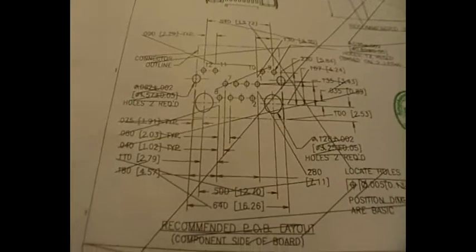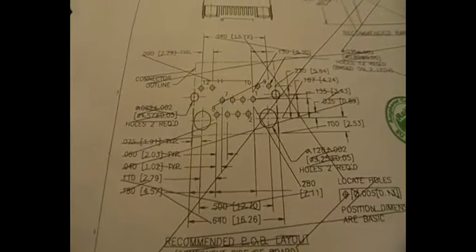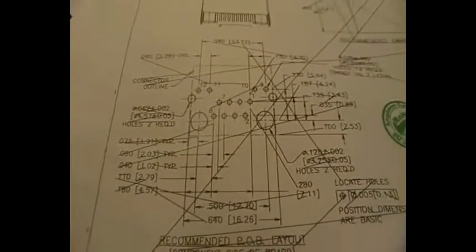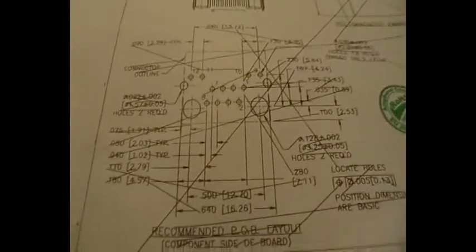In eCAD you've got the auxiliary origin, and some people change the grid for pads that don't line up on the grid. So some pads line up on the grid and you'll place them, and then some other pads are on some other grid and then you'll place them. But I tend not to do that, and I tend not to move the origin, but I find it really frustrating to have to take all these dimensions that they give you and do your funny adding and subtracting to find the actual X and Y coordinate that I want to use to enter it into eCAD.